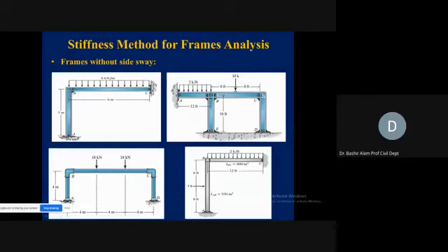The reason is, again, at A we have a hinge connection, meaning it can take horizontal as well as vertical reaction. And similarly, we have the same conditions at E and D also. So although the loading is unsymmetrical and the frame is also unsymmetrical, the support conditions are such that they are not allowing any horizontal displacement. So it means it is a non-side sway frame.